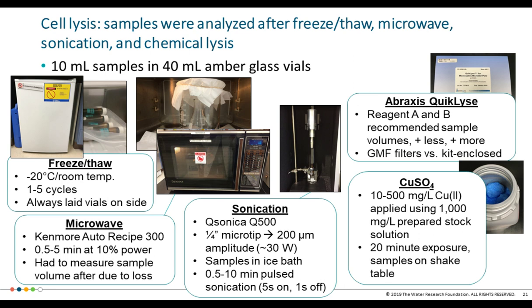We also looked at probe sonication. When we're talking about sonication, there's water bath sonication and there's probe sonication. Water bath sonication, from the literature, can introduce inconsistencies depending on where samples are placed in the water bath or how many are placed. With probe sonication, you get much more consistent results, so that's what we went with here.